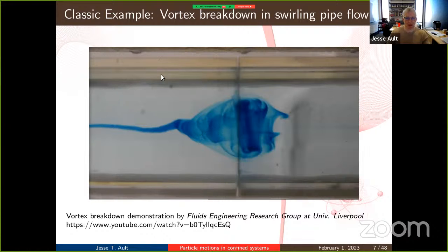If you take a cross section anywhere, the net mass flux has to be the same, just because of conservation of mass. You're injecting a certain amount of flow from the left. So what happens near the center plane is the flow has to increase speed on the outer rim of the pipe, because inside this bubble region, the flow is actually upstream in its direction.